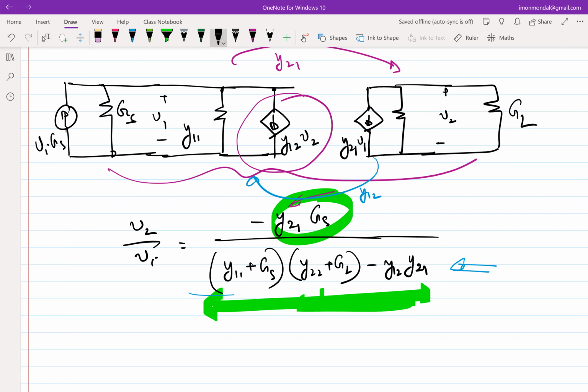And as it turns out, designing very good oscillators is also another research domain, and people have done PhDs on designing good oscillators. When you try to design good oscillators, you try to design systems where this denominator goes to 0 under certain conditions. So this is not necessarily a bad thing. For folks who want to design an oscillator, you are trying to achieve this.